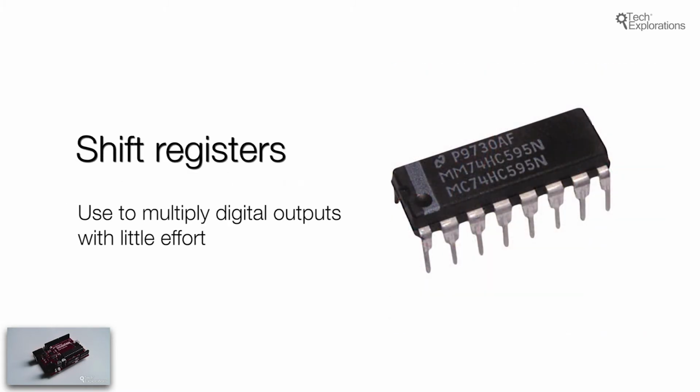In this lecture, I'll show you how to use shift registers to multiply the available digital outputs. In a later lecture, I will also introduce you to I2C-driven port expanders. These technologies make it possible to design ever larger and realistic gadgets using a single low-cost microcontroller. In both cases, shift registers and I2C-driven port expanders allow you to reduce the amount of Arduino pins tied up for a particular peripheral and delegate the control of those peripherals to external controllers.